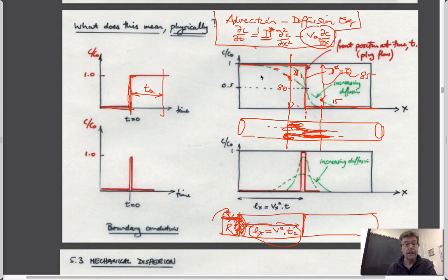Okay. We could think of this where you dump stuff into the ground and you leave it there, and it's there to dissolve over a very long period of time because the rate at which you're removing it is very small, just like the example you're doing in assignment 4. Or it could be a plug that's put in maybe as an aqueous component. Maybe you put a mixture of gold dissolved in water into the ground, or iron dissolved in water like you would with acid mine drainage, and it's not coating the particles as a continuing source that gets renewed as you flush it out.